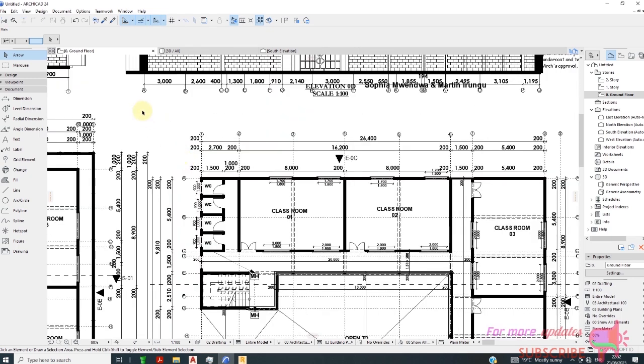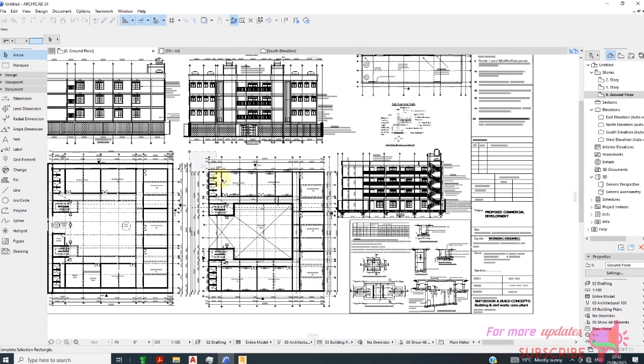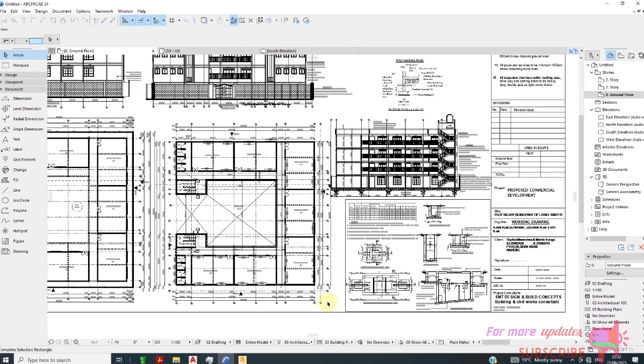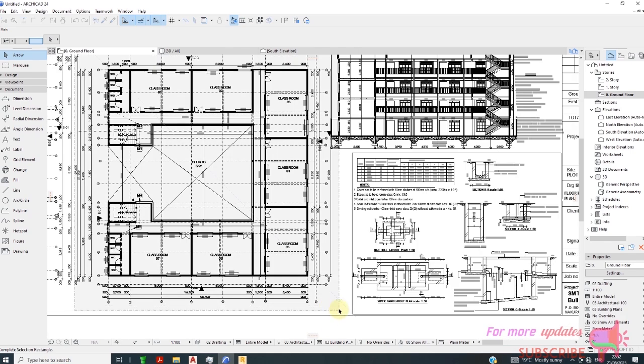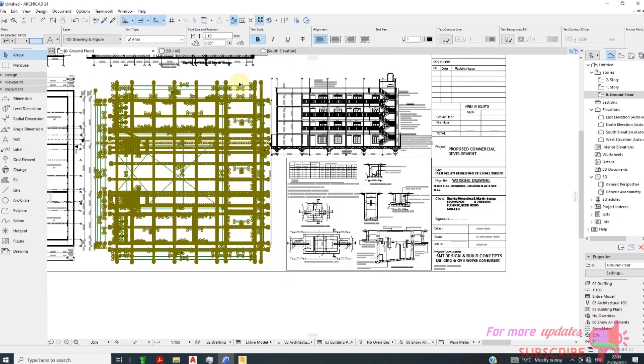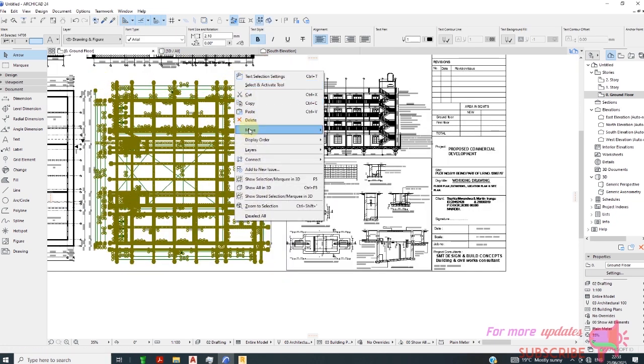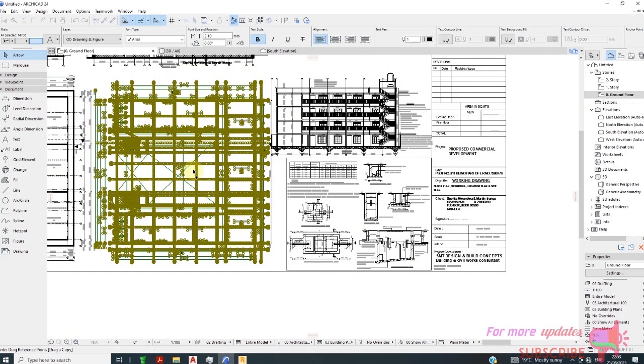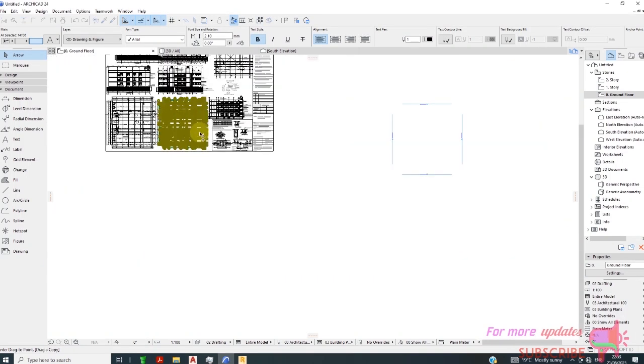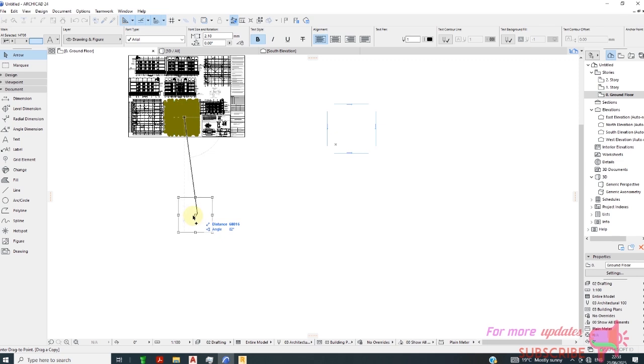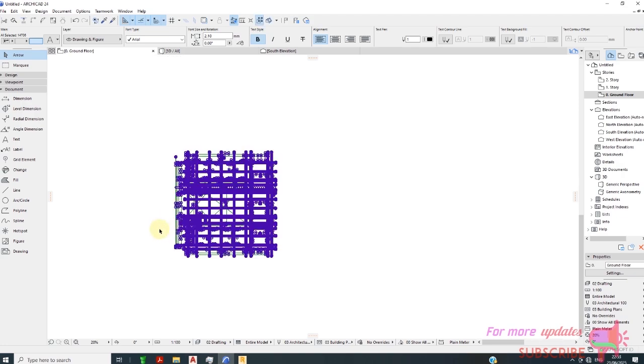I want to copy these below here, these typical first and second floor. See if Autocad is going to give us something better without that difference. Then I want to drag a copy, right click, move, drag a copy. I'm not sure it's to scale. We can just scale it. There is no problem. So we have dragged a copy down here.